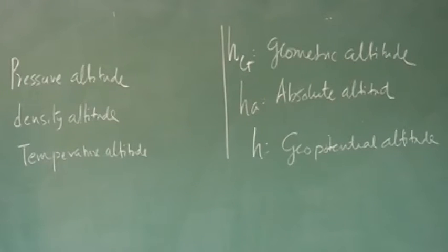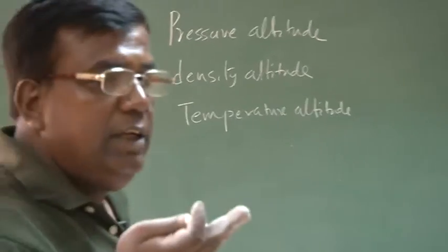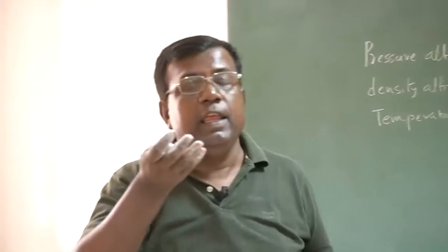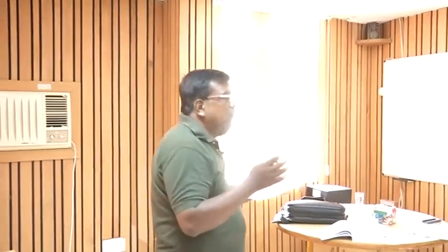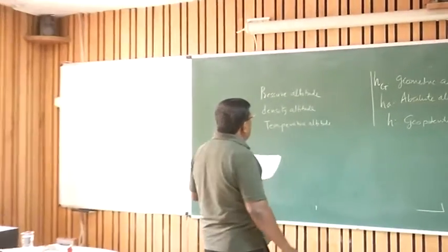What are these? The principle of altimeter is it senses the static pressure locally at that altitude, and that pressure is calibrated and some number is recorded, right? Either through analog or through a digital, right? But that is not the pressure altitude.